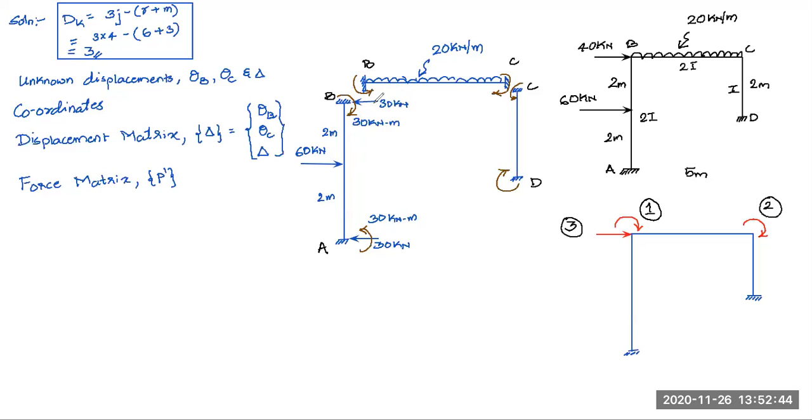Okay, to find this reaction, I have to consider moment about A. So this is minus 30 anti-clockwise plus 30 anti-clockwise, which cancel, and then 60 into 2, everything divided by 4. That is, this member's free body diagram should be taken along with these fixed end moments, and then you should go for determining the reactions. So that will be the reaction. Since these two moments are the same, they will cancel each other. I'll get directly 60 into 2 divided by 4.